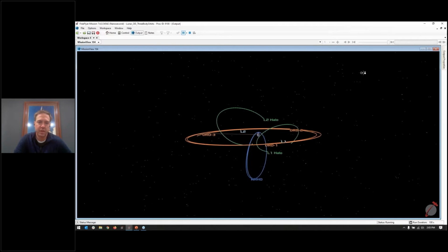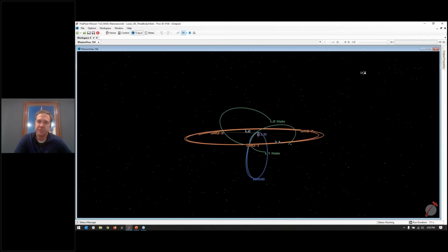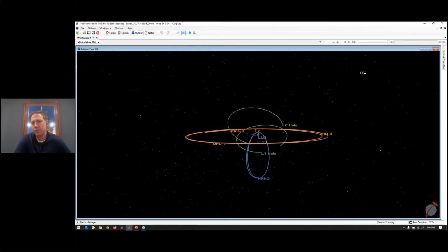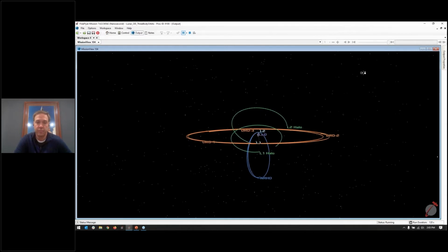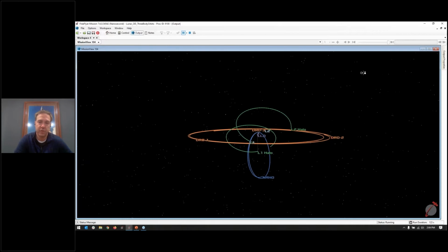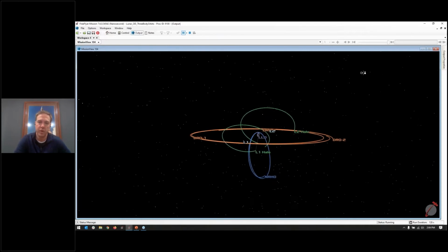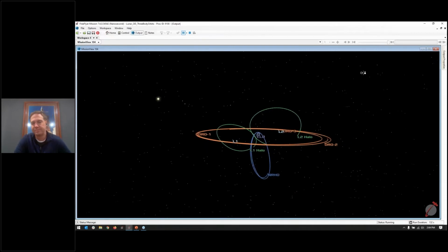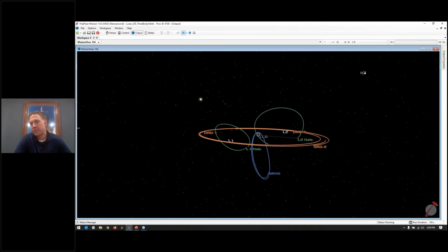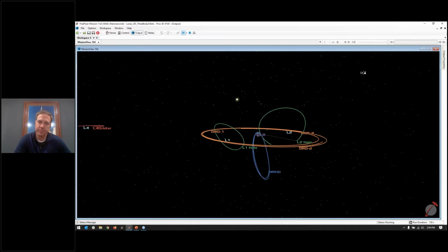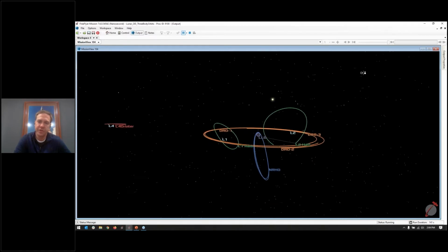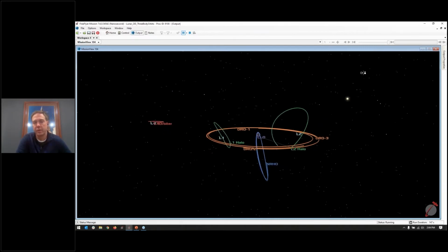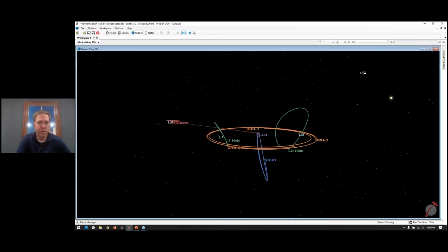For the analysis that I'm presenting, I chose a constellation of distant retrograde orbit satellites, mainly for their dynamical stability and the ability to provide stability of orbit without any sort of maintenance maneuvers, whereas other halos will require maintenance maneuvers at varying frequencies. They also provide a very convenient diversity of geometry for the NRHO orbits in particular, and that factors into the navigation analysis I did.